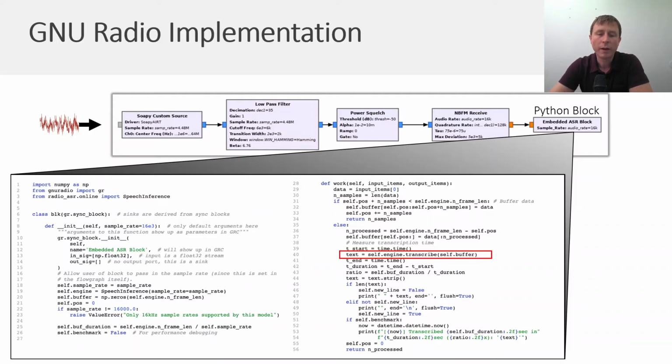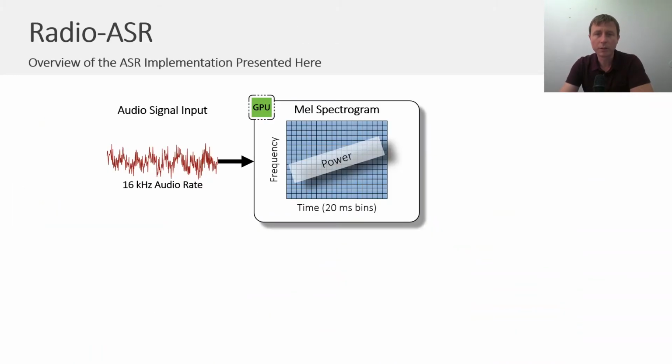The reason why basically everything is contained in a separate function is because we have to leverage GPU compute in order to do this. And as of right now, GNU Radio does not handle GPU buffers, so we kind of have to put it all into one big blob of Python code, so to speak. But let's look at what that big blob of Python code looks like.